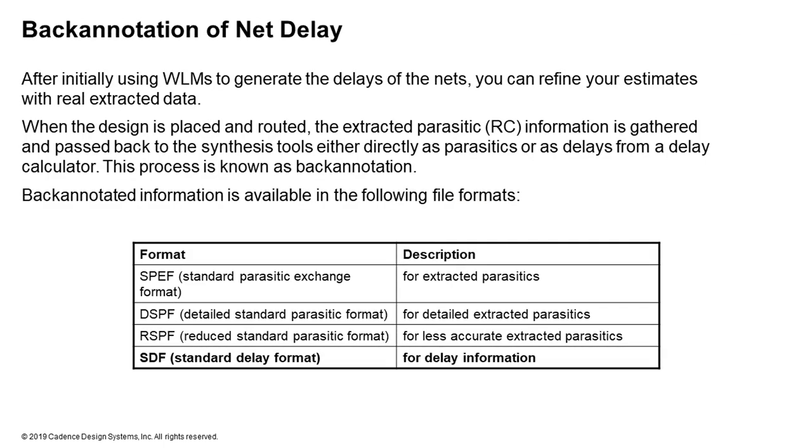So initially when you start out with your synthesis, you're using the wire load models, but then when you get to your place and route, and your place and route is done, then you can generate the extracted data, which is either in the form of a SPEF or an SDF.